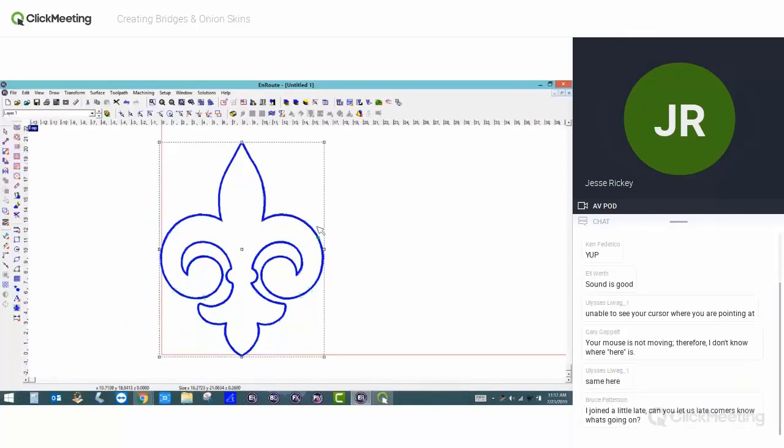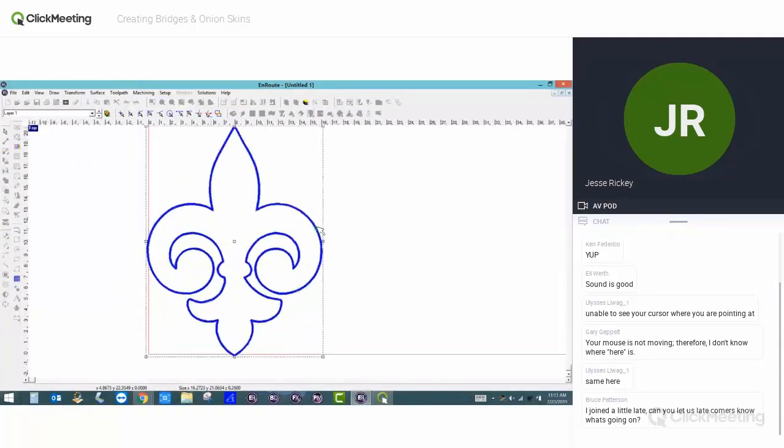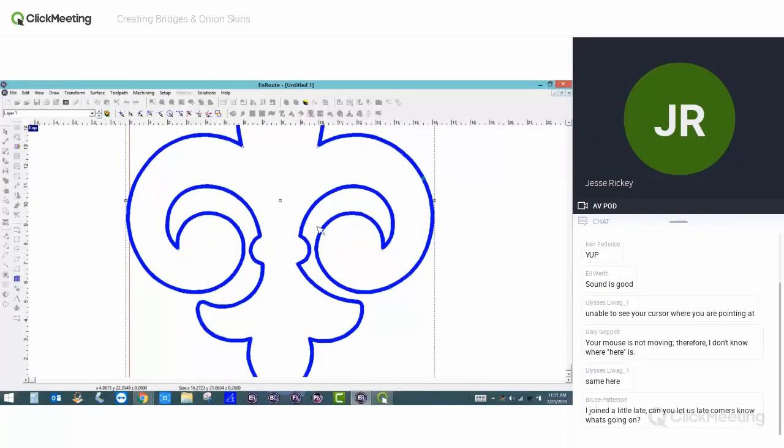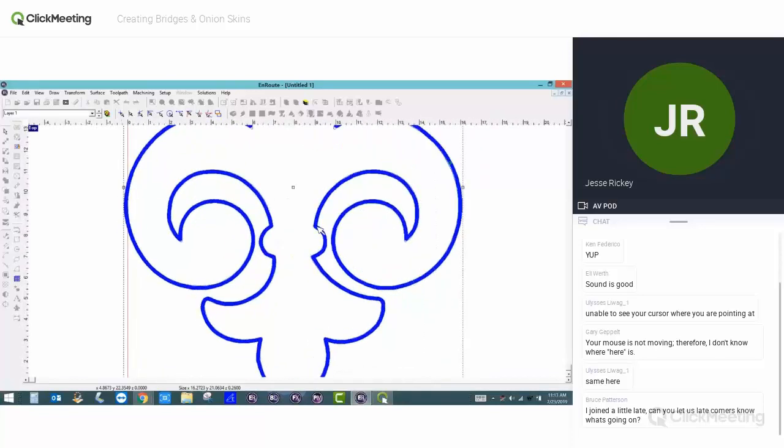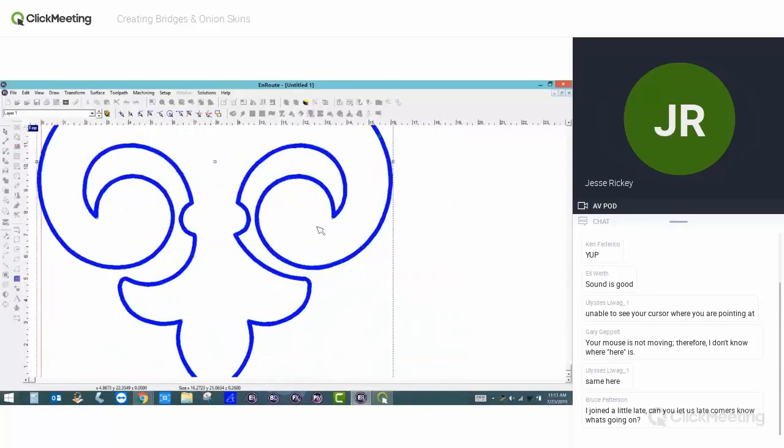Inside here, I'm going to select my part, and then I'm going to go back into the toolpath menu, and I'm going to go back into my edit bridges. Inside here, I'm going to delete this bridge. Once you're in the edit bridge menu, you can right click inside of another bridge and you can delete them out if you choose to. Maybe it's holding down too much material or it's just not necessary. Part's not moving as much as I thought. I can go back and get rid of them if I choose to.